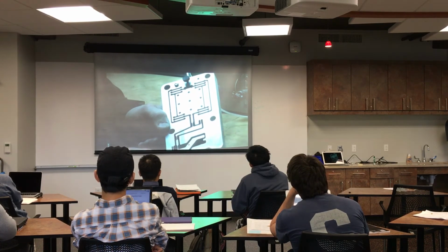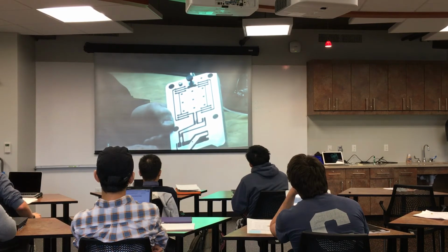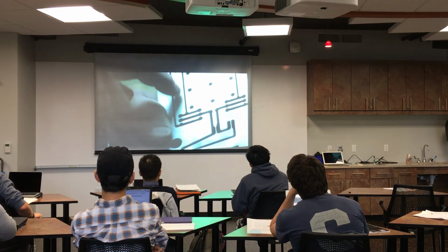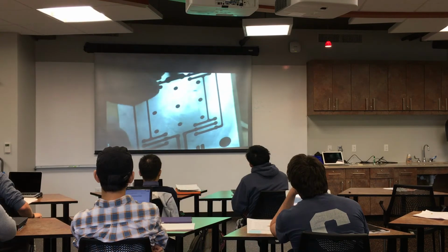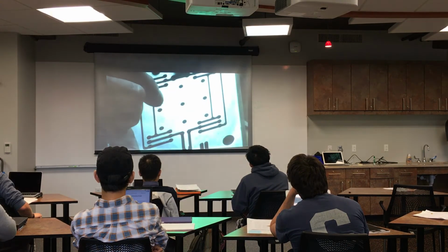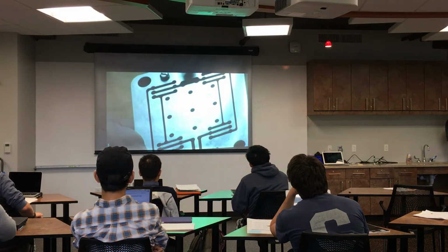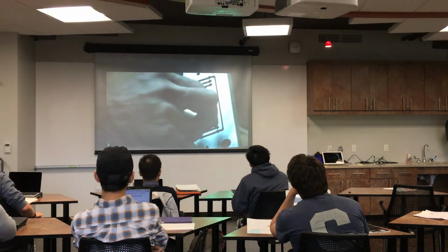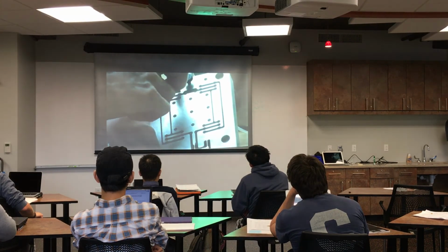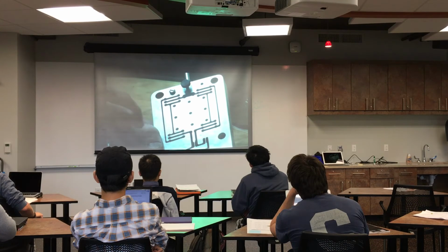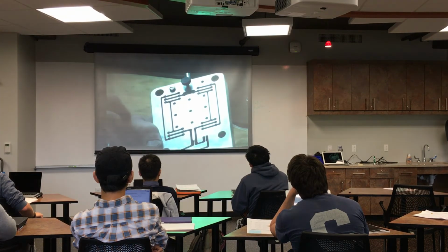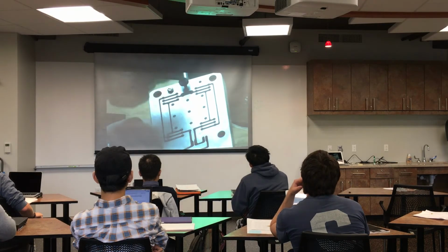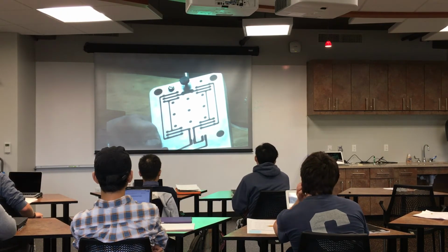If you want a very high accuracy flexure, you really should pre-drill the holes, because how well this moves and how linear it is, how much it follows a straight line, depends on the exact matching of all the pivot points, or the elastic pivots. Now the water jet isn't accurate enough to give you a straightness in the range of 1 micron.